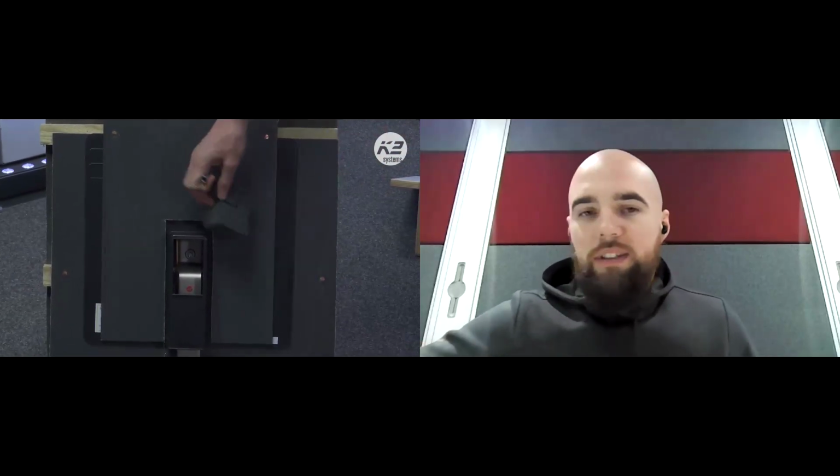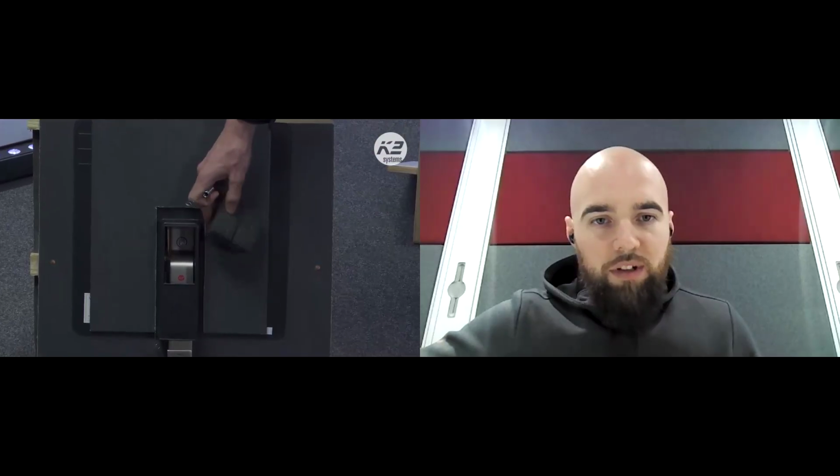That one actually uses our 214 roof hook, which is one that's quite common in the UK. So that sponge just wraps around the hook and slides up, kind of stuffed up into the actual roof solution. So that stops any water ingress. And so that hook there is the 214. That's used for slates when there's battens present. We do have the other variant which we can use, but that's the 373 roof hook, and that is the one that Ciaran showed, which is flat.